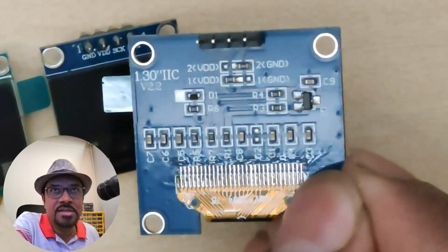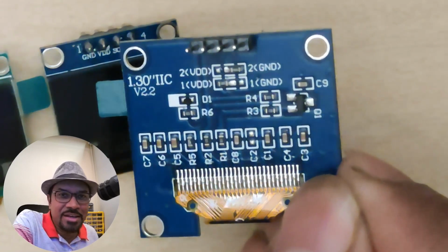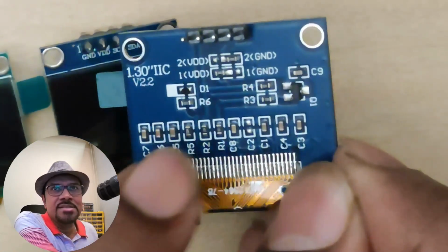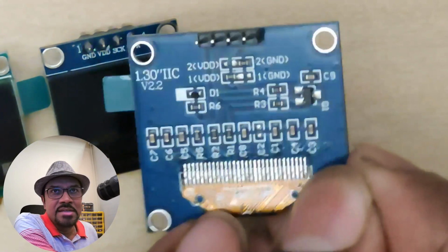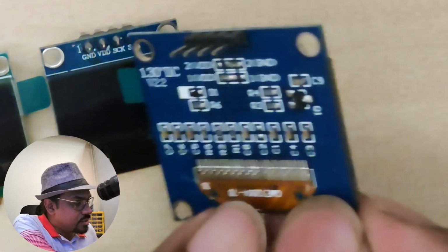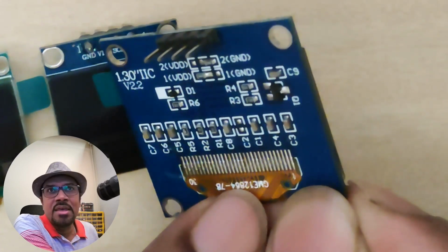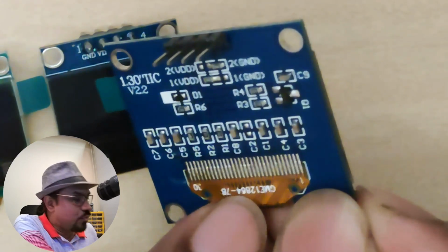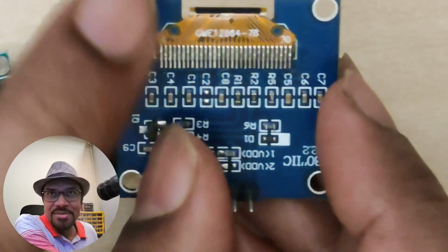So if you randomly get the display, you cannot make any assumptions because when you look at the back, there's nothing much being shown up here. You can see this in my Zoom screen. It just shows up 1.3 IIC, there's I2C connection, and it tells you about a couple of these labels for all the resistors and so on. I also saw this number, and this number is nothing to do with the display, I guess. It's got to do with this actual OLED display itself, not the display controller that's sitting behind it. So it looks like it's the OLED display's model is what you see. I can see that as GME 12864-78. But then if you see, this is actually based on the SH1106 driver. That's what works for this.